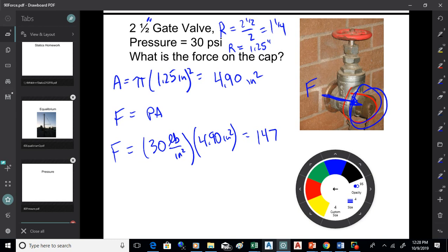Right. So now, I think one thing to realize is this: if you're doing this, a major part of the cost is digging it up. Digging's what costs money. Okay, so City of Albany, I think, approaches it the proper way. They dig it up, they replace it. They don't mess around with fixing water services. They replace water services is what they do, because they figure if there's one problem here, in 3 months I'm going to have to dig it up again and fix another problem. So they just replace is what they do. Okay, and that just means putting in a new saddle, maybe. Okay, a new corp stop, service line, new angle stop. New meter, or maybe not, yeah, new angle stop, and then tie that into the meter. Okay, so that's kind of the deal with that. Okay.